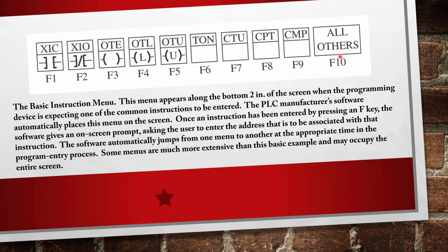One of the beauties about PLCs is, let's take our process where we're weighing and measuring and painting, diverting those boxes. If I want to make a change to that process, that's probably going to mean I'm going to have to do some rewiring. Maybe the wires don't fit anymore, so now they're too short. I've got to cut new wire and throw the old ones away. Maybe I need more relays or relays with more contacts. If I make changes in logic that's made out of hardware components, then making changes and additions to that logic is usually expensive and time consuming.